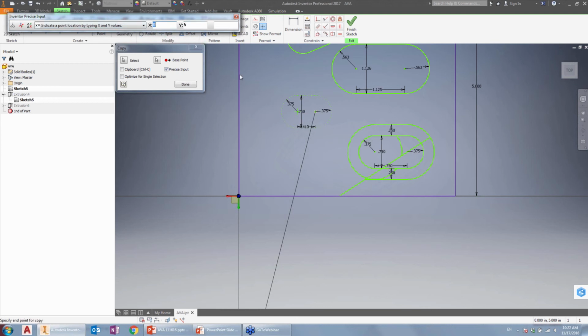But if you type in other things, it goes based on where your base point was. It doesn't actually go in the direction of your base point. It just goes off the coordinate system of the origin, and it'll go to precise points. So you kind of have to look at your X, Y, Z axes from your origin. As you can see, the green is your Y axis, and I believe the X is that red axis there.